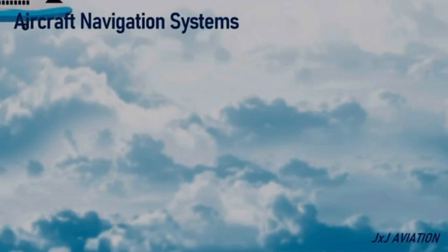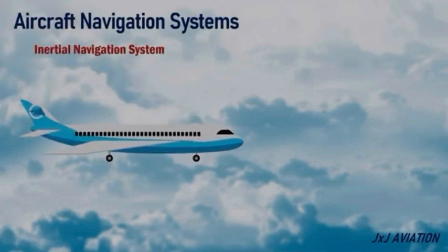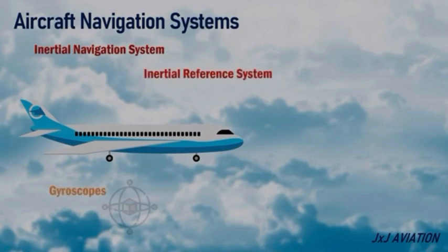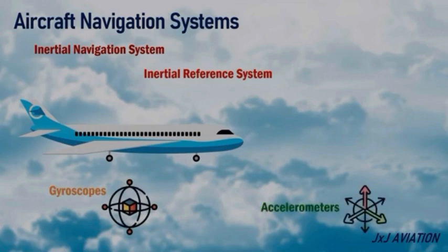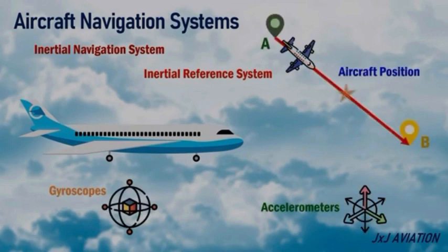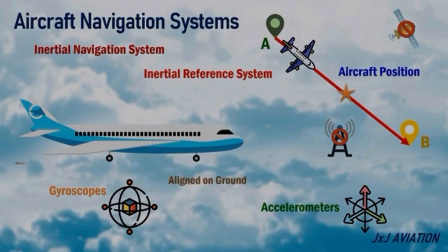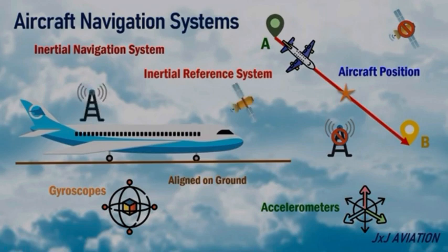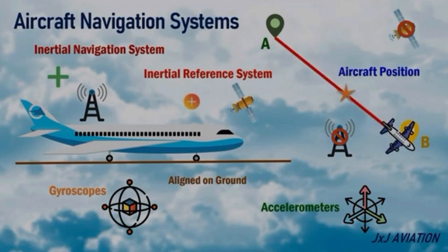By heart, we know that all aircraft have some sort of navigation equipment, because without navigation equipment on board the aircraft we cannot fly. But the question is, does the navigation equipment on board the aircraft meet the specifications and the requirements of the PBN, the area navigation, or not? If not, we can fly, but not in some designated areas. We will not be able to perform some instrument approaches related to the RNAV or to the RNP, because we cannot meet the specifications of the PBN or performance-based navigation.